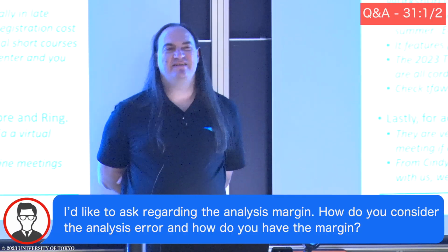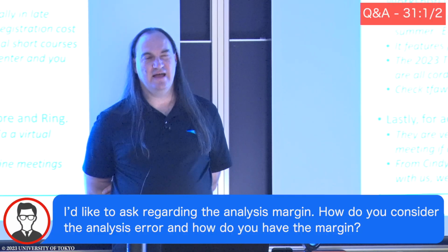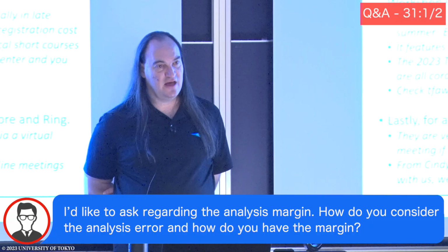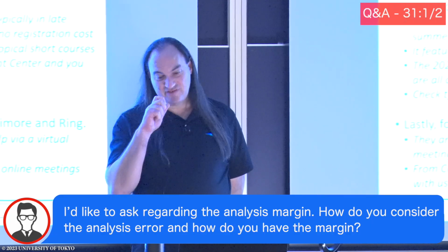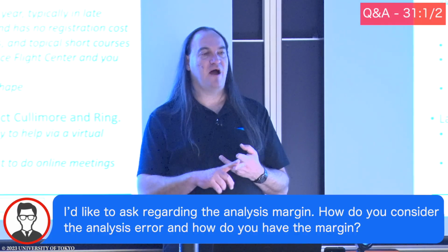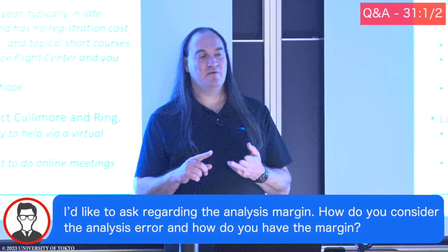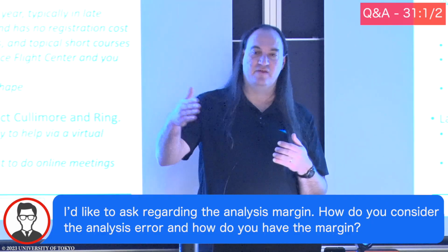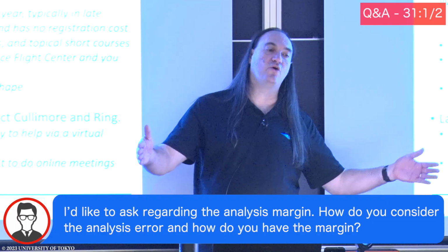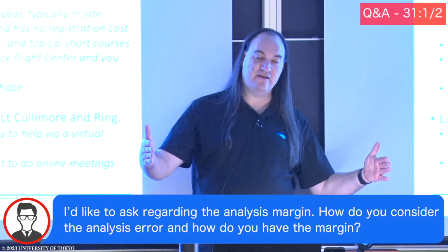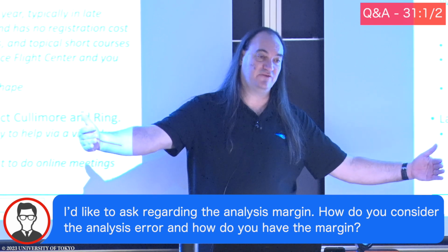So error is very difficult to quantify. Usually our standard practice is we stack up all the worst case things and then hold margin to the stacked worst case. So we look at what's the worst beta angle, what are the worst case properties for alpha and E, what are the maximum dissipations we might have, what are the largest E stars we may do, and we stack all that up, and then we go the other direction, what are all the coldest things, and make sure that that falls within 5C of our design requirements.